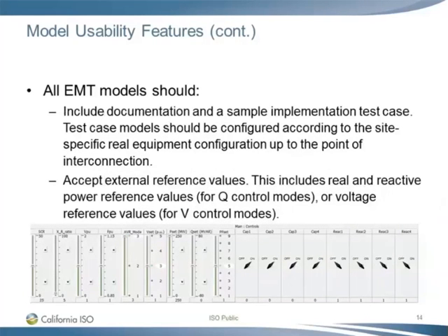All EMT models should also include documentation and a sample implementation test case. Test case models should be configured according to the site-specific real equipment configuration up to the point of interconnection. They should also accept external reference values. This includes real and reactive power reference values for Q control modes or voltage reference values for V control modes.